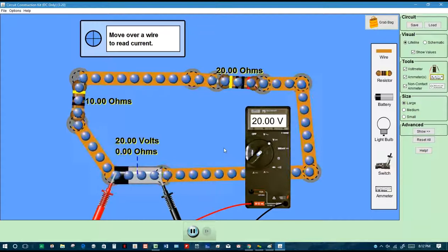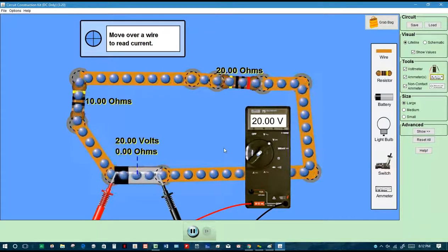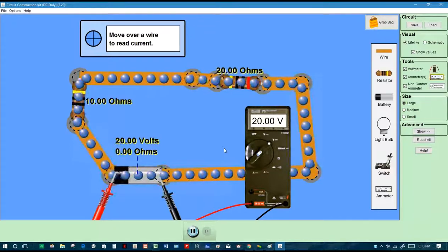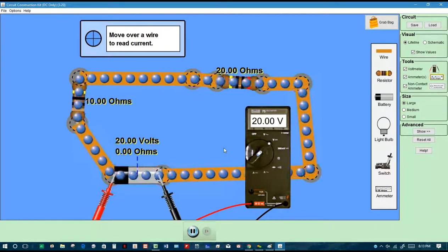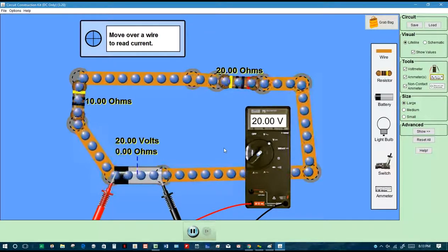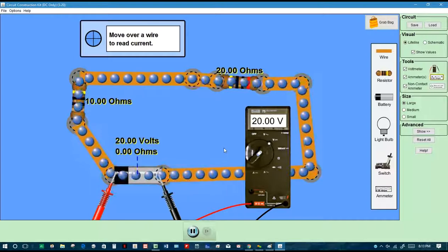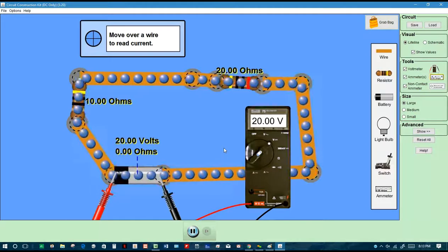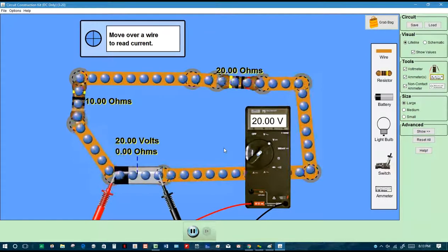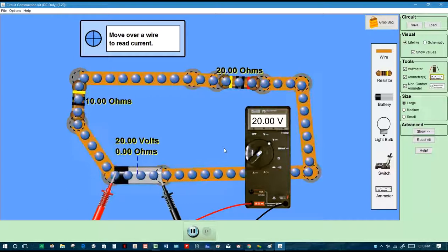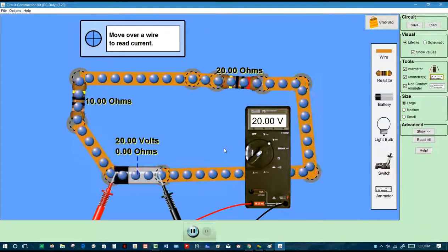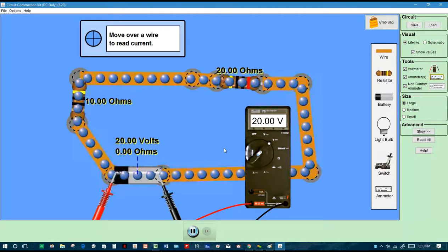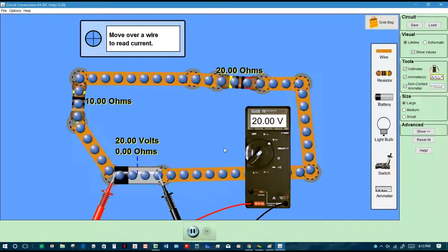You can kind of think of voltage as a collection of electrons inside of the battery, right? They don't want to be next to each other and all piled up on that plate. They repel. Coulomb's law says electrons repel electrons. So when you give them a path to get off that plate and start flowing through a circuit, they're going to take it, because they're in a very high energy state, all piled up on a metal plate very close to each other. That's the idea of voltage: it's the collection of similar charges in a small space.